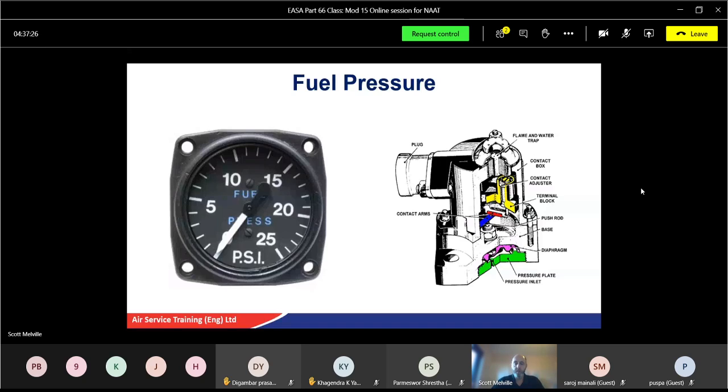Okay. Most fuel pressure is indicated by a light operated from a pressure switch rather than a pressure transmitter. You might have a fuel differential pressure transmitter right beside a fuel switch. So we just need to know when the fuel pressure is not there, but we can also have a fuel gauge that actually shows how much pressure we've got in there as well. The switch will be a capsule diaphragm, again, operating a set of contacts at a predetermined value.